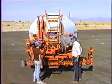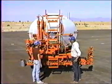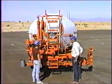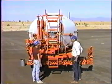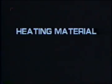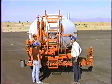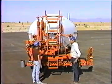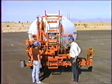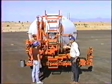First thing that we're going to do anytime is to get the material to come out of the tank into the piping system. And the first operation that we'll probably do on the machine would be to heat the material in the tank. Anytime that we're heating material in the tank, we want to circulate the liquid in the tank. That is, we want to move it from the back of the tank to the front of the tank. And we do that in order to keep cool material moving past the heat tube.